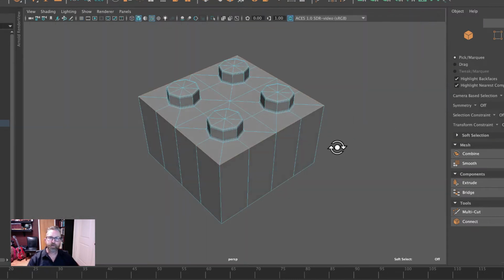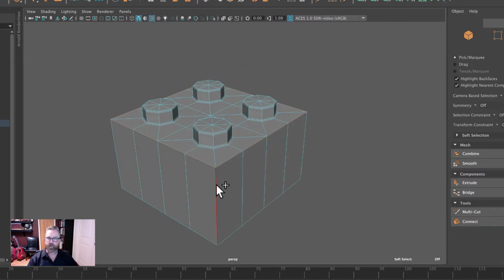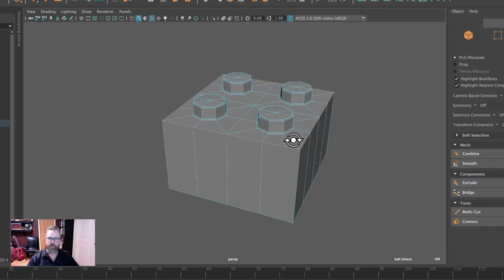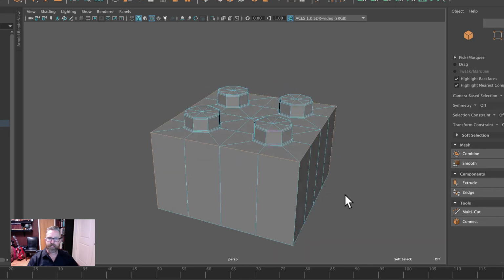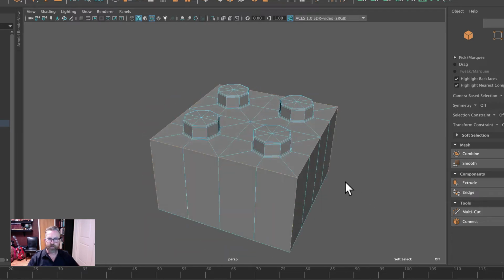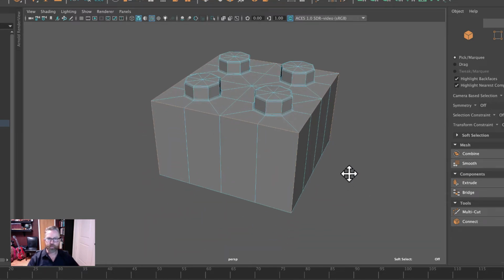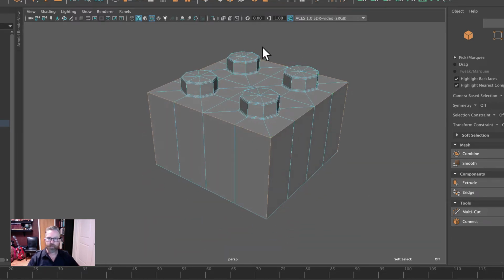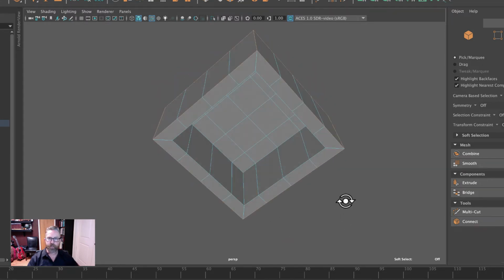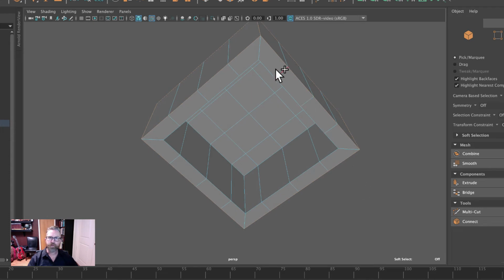So we have to revert back to our manual selection. In this case, let's just go through. Last time I selected all of the squares and rectangles first, then we got the outer edges. This time, let's just go down through the selection. So I got that top square. Corner edges, we'll shift double click that bottom square.